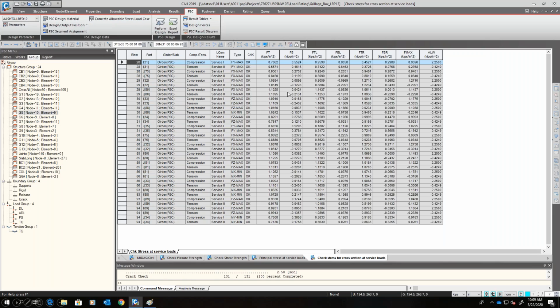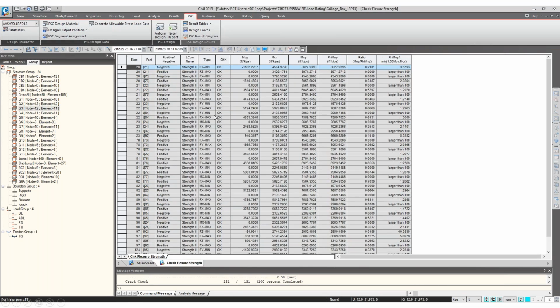Here, the software has the capabilities to check the stresses. As you can see, all the stresses here are in kips per square inch. All the checks work for this particular design. As an example, I'm showing the results for girder 5. For another example, I'm using girder 3 now for checking flexure.